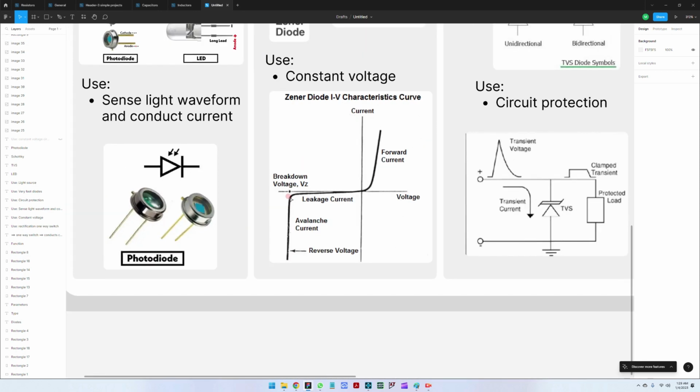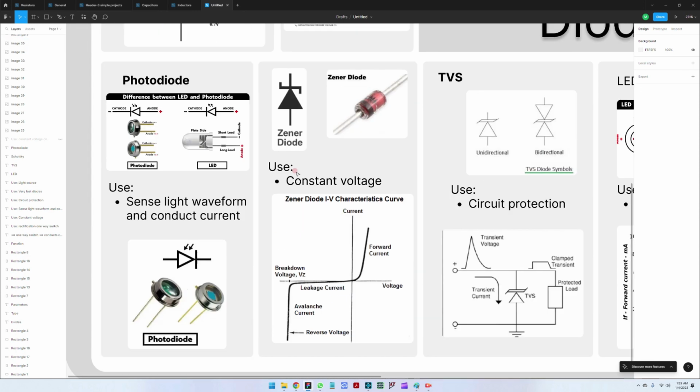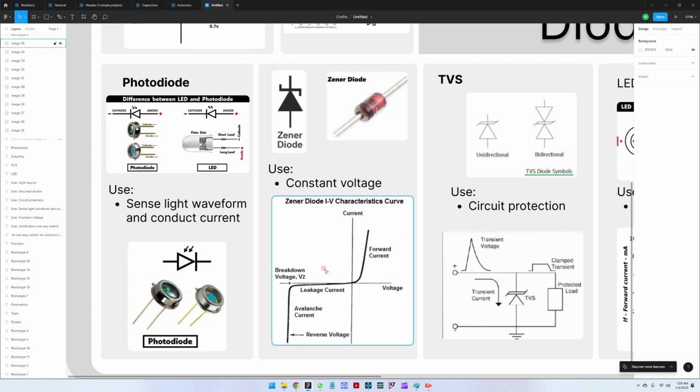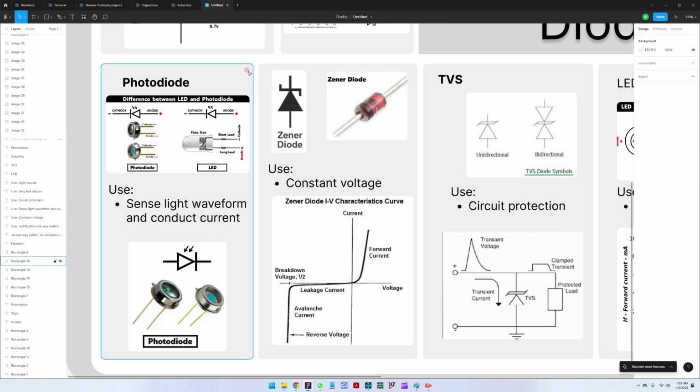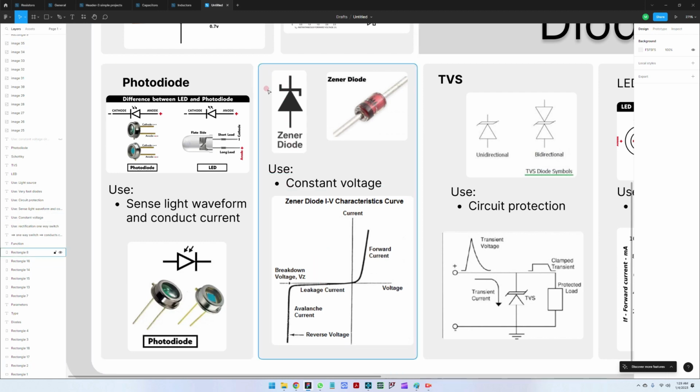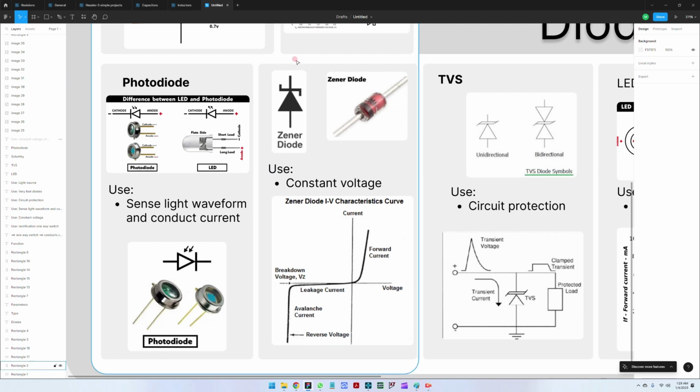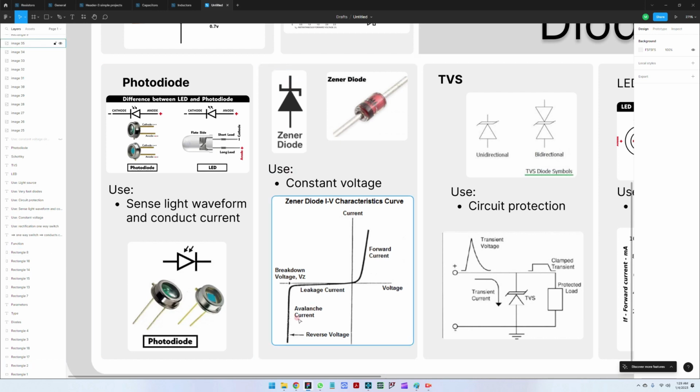So, for example, you would see a lot of Zener diodes that are 5 volts, and this diode would act the following way. When you're supplying this from the cathode to the anode, let's say you have a power supply here. When you reach with this power supply the 5-volt limit, it will start to open here and will allow current to flow through it.